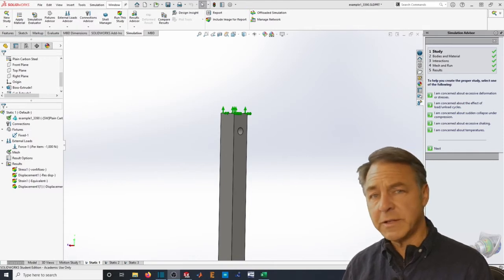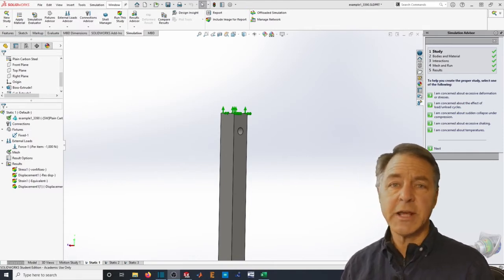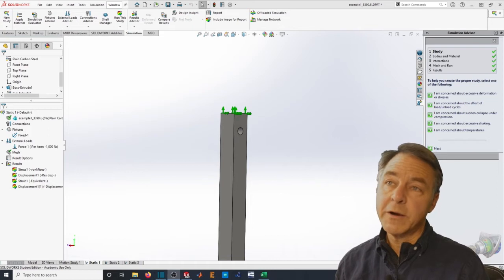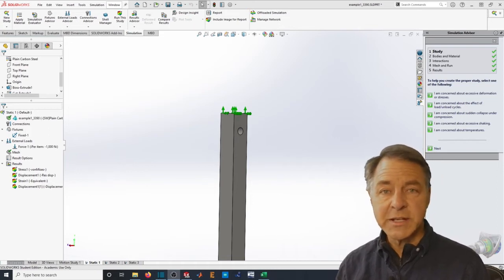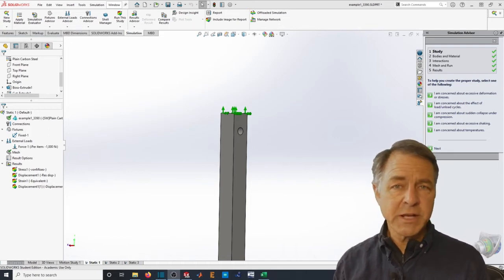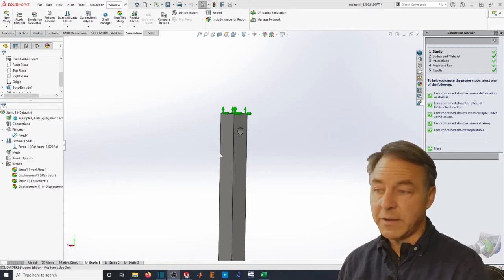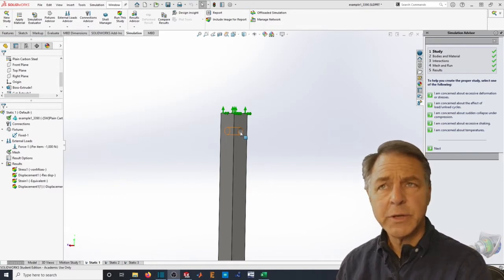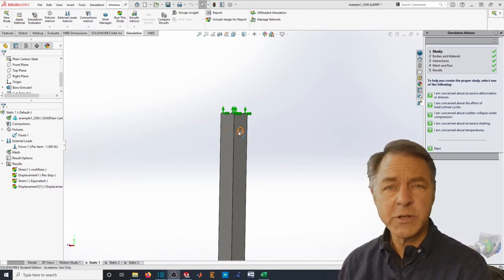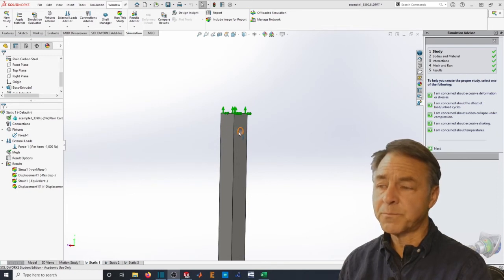You have to look at the details of the simulation and look in particular where you should expect to see features that make sense. For instance, in the area around the hole that I created, the hole was in the middle, so there's no reason to expect that the result would not be symmetrical about the hole.